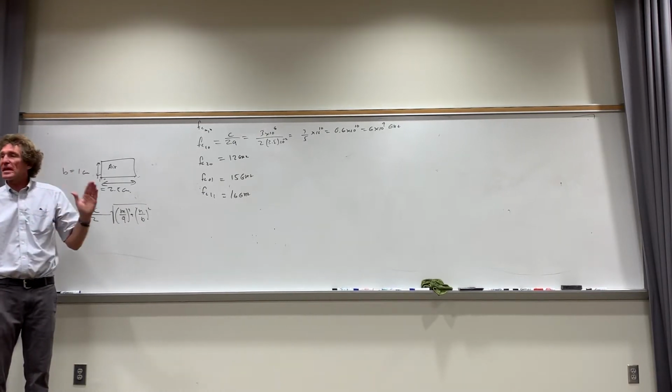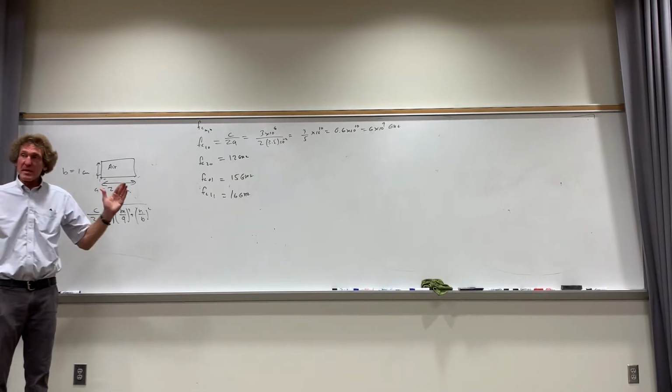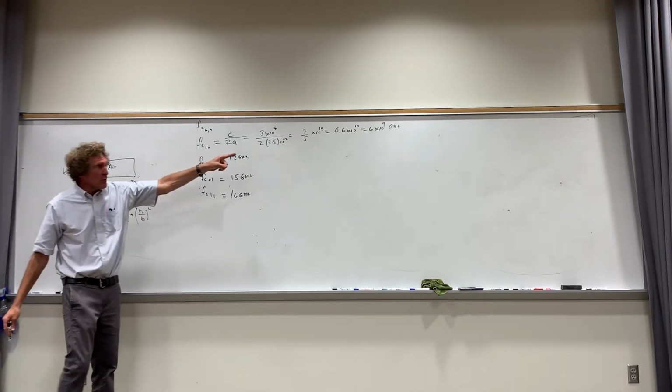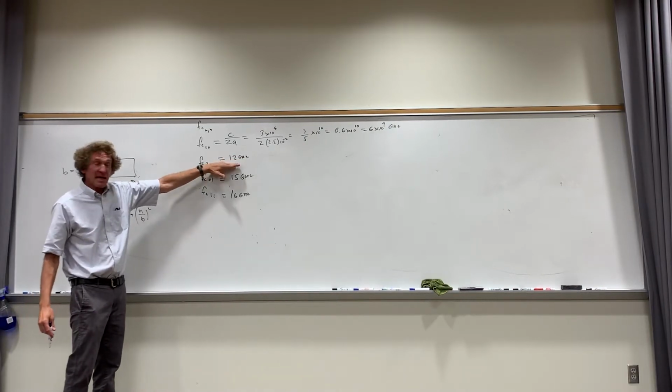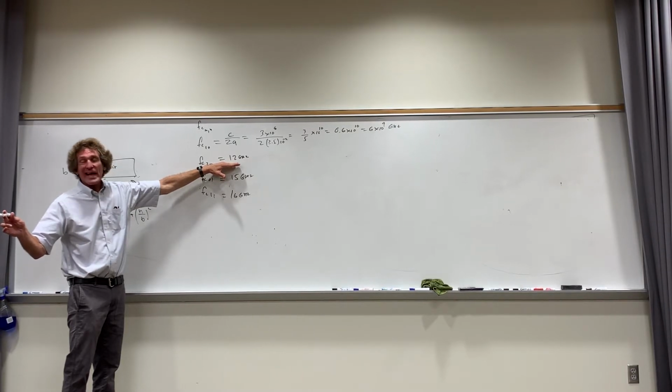Almost always, the reason they have those dimensions is so that the next highest mode will be clearly separated. The low frequency is 6, the next mode comes in at 12. So operating at 10 gigahertz is safe. Follow me? Or at 9.5 gigahertz, which is typically done.